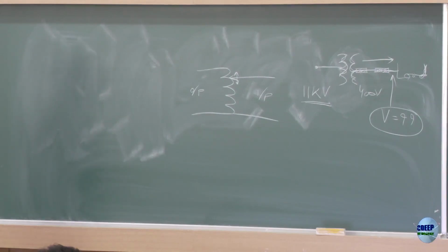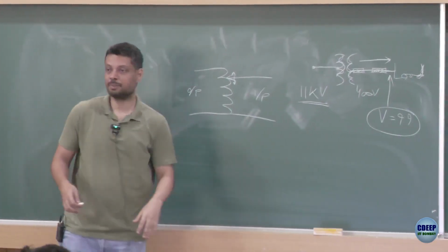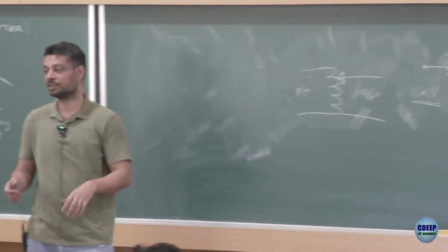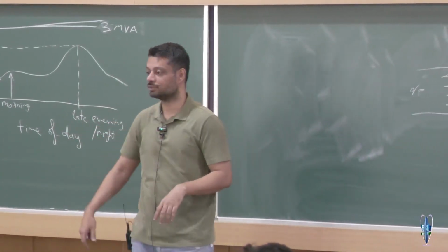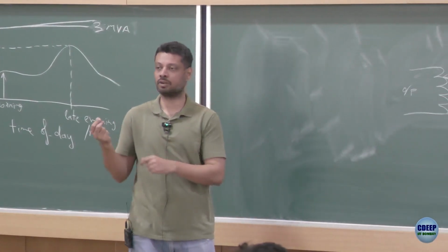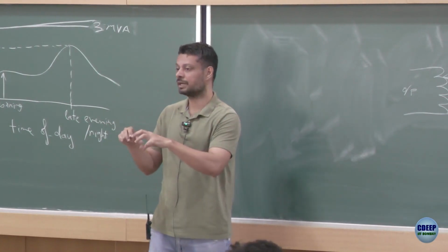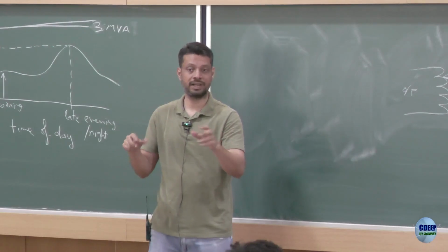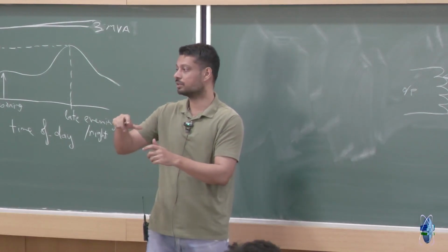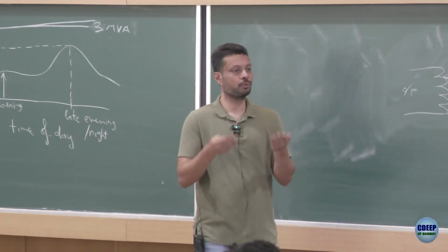But now the question is, what is economical, what is practical? It is not practical or economical to have it in every room. Manually doing it would be really painful, right? You can put a small motor, connect it to a small microcontroller, measure the output voltages, and write a small code so that whenever the voltage is less than some point, you turn the stepper motor by a certain angle. That would be a small closed loop system which would operate.